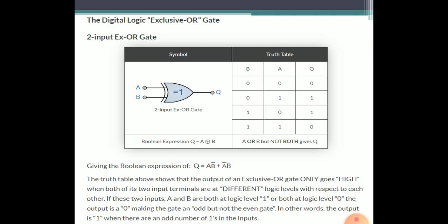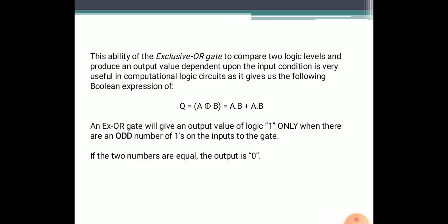A dash B. The exclusive OR gate function or XOR is achieved by combining standard logic gates together to form more complex gate functions that are used extensively in building arithmetic logic circuits, computational logic comparators, and other error detection circuits. The two input exclusive OR gate is basically a modulo 2 adder, since it gives the sum of two binary numbers, and as a result is more complex in design than other basic types of logic gate. You have seen the truth table, the logic symbol, and the Boolean function obtained from this gate.